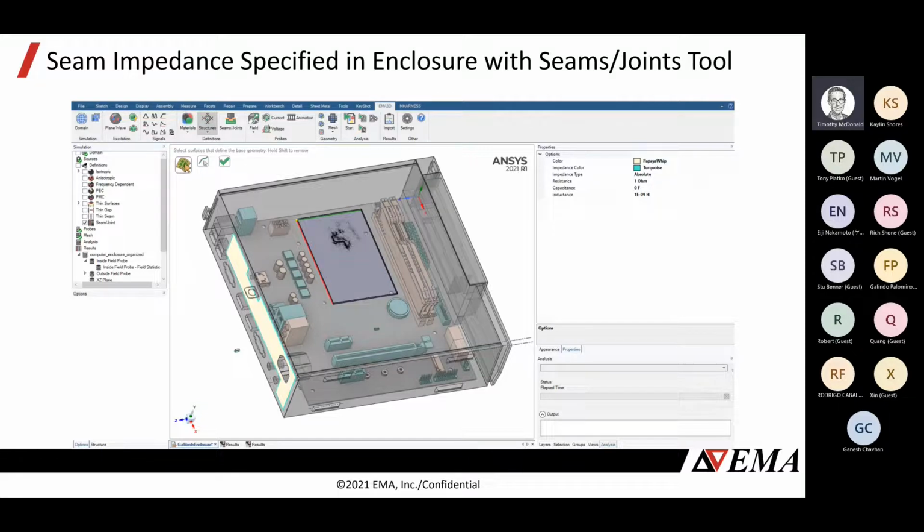Whenever we have a mechanical interface, there's always a manufacturing tolerance. So unless you've put a gasket in an enclosure, you're always going to have a gap between interfaces. But those gaps might be tiny. They might be micron size. However, they could be very important for EMI/EMC purposes. What do we do? Do we want to make our mesh try to resolve something that's micron size?